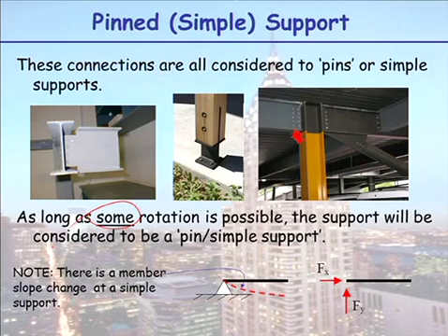So you may say here also, there's some fixity here. We have 4 bolts in here. Because it's not fully rigid, we take it to be a pin. We idealise it as a pin. So when it comes to a pin connection, there now is rotation at the support.